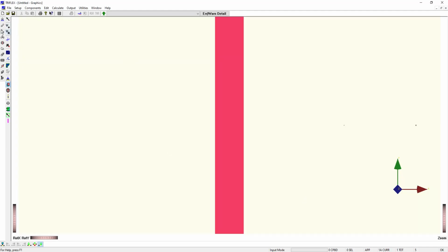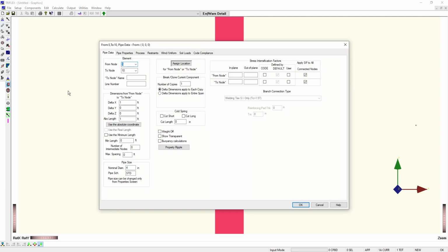Let's do a pipe. We're going into the -Z direction, so we're going to pick up a pipe at the component toolbar. Notice that our component toolbar is anchor, pipe, elbow, valve, flanges, reducers, joints, expansion joints, release component. The release component is kind of like a C node. It's basically a component that defines the relationship between any two other components.